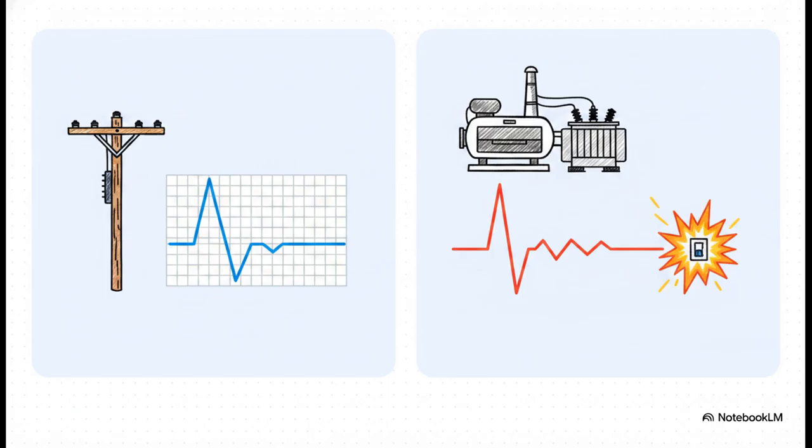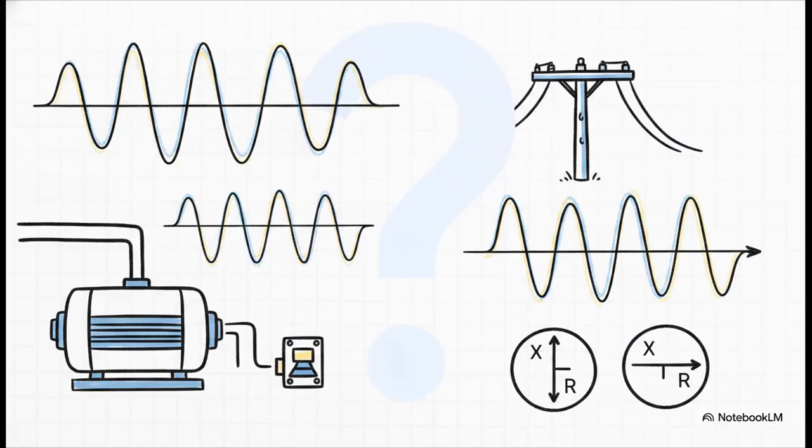And this is absolutely crucial for breaker selection. A breaker rated only for symmetrical current might literally blow up on a high X/R system. Why? Because the actual peak current it has to interrupt, including that lingering DC offset, is significantly higher than the RMS value alone. So let's do a quick mental check. A fault near a large generating station shows current still highly asymmetric after 3 cycles, while a fault way out on a distribution feeder looks symmetric almost immediately.